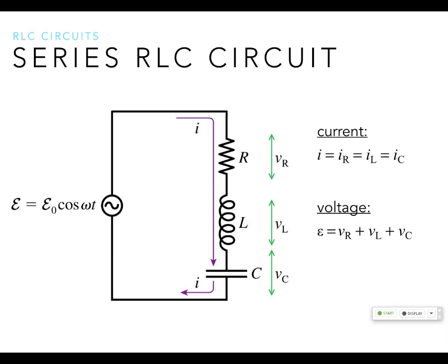But remember, in a series circuit, what is the same through everything? Current. Okay. So the instantaneous currents should be the same through everything in your circuit because it's a series circuit. And that's why we start with the series circuit. You have this one thing you can be sure about, which is that the instantaneous currents are the same. And the instantaneous voltages, remember these are lowercase v's, should add up, right?